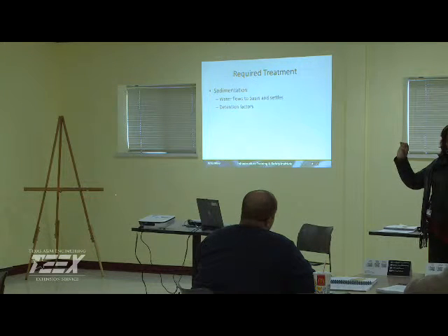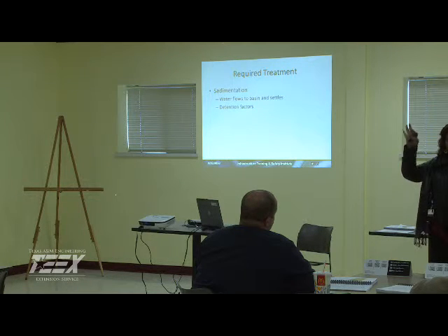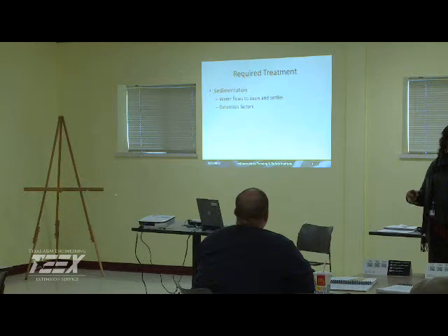Yeah, and where is it clear usually? At the top. If I let it sit there, let's say 5 minutes longer, will I have a greater amount of supernatant or top that's clear? You should, yes. If I let it sit there an hour or so, will it pretty much settle all the way to the bottom? You should, yes. So that tells us the longer the detention time, the greater the settability.